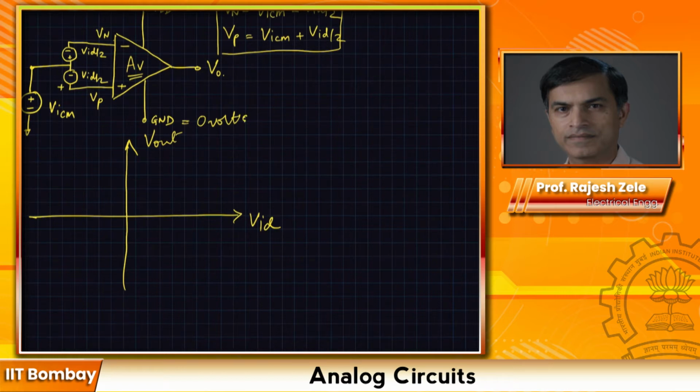For the sake of discussion, I'm going to call this 0, and this will be my VDD. If I apply VID, then we can call this center point, which is VDD divided by 2, our analog ground, around which the output can be. In this particular case, we can say that if the VID goes up, this is what the characteristics will look like.